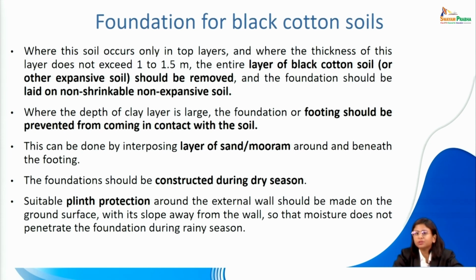Suitable plinth protection, as I mentioned earlier, will have to be applied on the external wall at the ground surface, and it has to slope away from the wall so that the moisture does not penetrate the foundation during the rainy season, because when expansion happens, it is possible that the water can actually enter this area that you've created to cushion your footing. So to prevent that, plinth protection is very much required in this context.